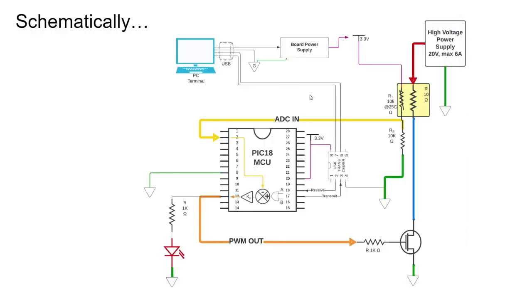Back here to our picture, the logic is represented here as implemented within the device, the analog to digital conversion sample. The thermistor is a very simple circuit. It's nominally 10 kiloohms at 25 degrees C, 10 kiloohms to ground. It's called a negative temperature coefficient, which means as it gets hotter, the resistance goes down, so this value goes up. We're sampling that here. This was discussed. Here's our negative feedback, A or B, based on my choice in that example, of set point, negative feedback, application of the proportional gain, and a PWM out,